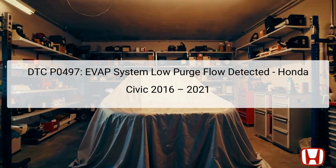The error code P0497 indicates that the vehicle's evaporative emission control system, EVAP, is detecting low purge flow. This system is crucial as it captures and recycles fuel vapors from the fuel tank and prevents them from escaping into the atmosphere. A low purge flow condition can impair vehicle performance and lead to emissions control issues.